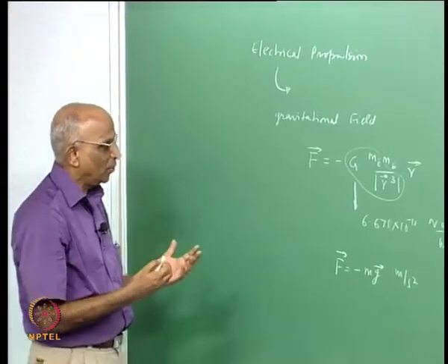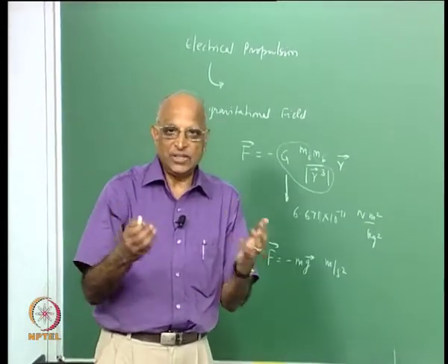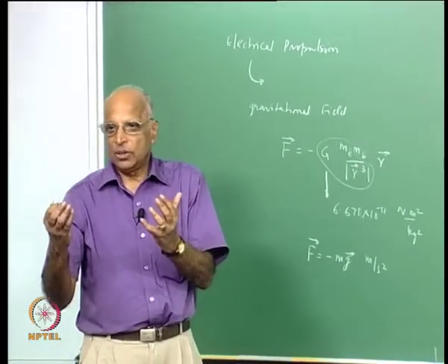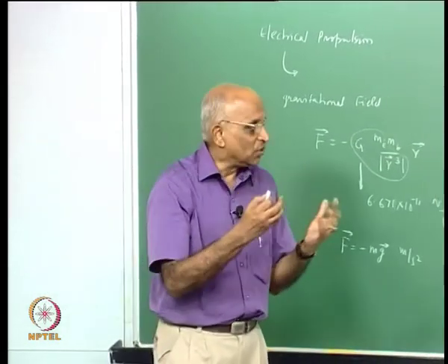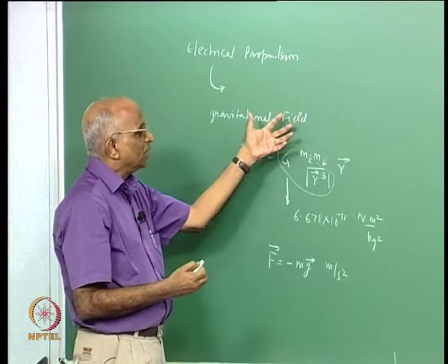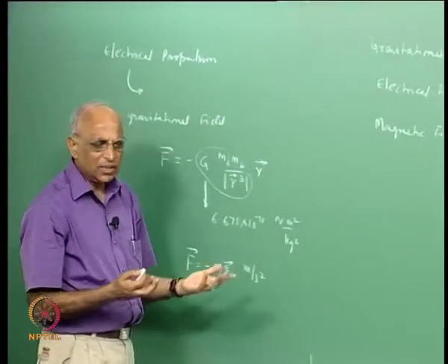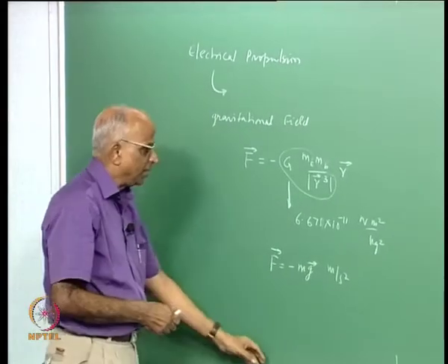And while doing so, in the same way we derived that chemical propellants have these characteristics, a low molecular mass, a high temperature is what we require. Can we put some requirements for things when we want to push something using electrical and magnetic fields? That is what I will be doing in today's class, right.